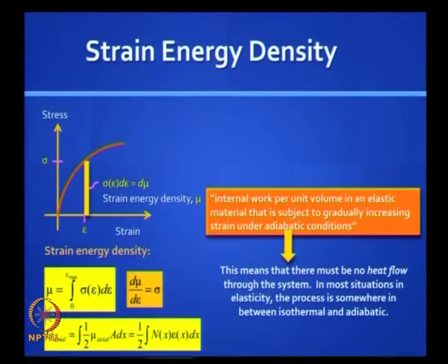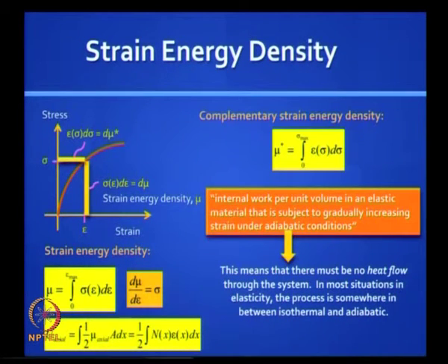With this assumption, if you integrate the strain energy through the volume of a bar, let us say subject to axial tension, then you get the classic equation: half, if it is linear, half integral axial force times strain, integrated over the length of the bar. Okay, so there is another term which is called complementary strain energy density.